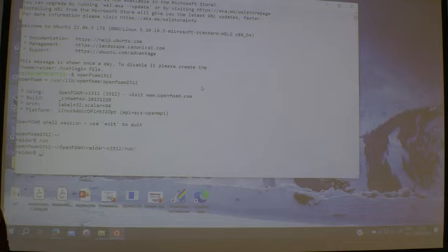Let's find it. Echo, and then $FOAM_TUTORIALS. Oh, it was under usr lib. Okay. Copy -r /usr/lib, and under lib it was OpenFOAM, wasn't it? Yes, should be. OpenFOAM, and here I should have tutorials.